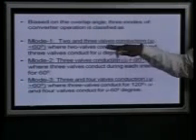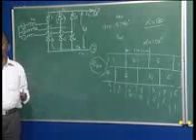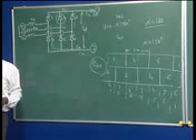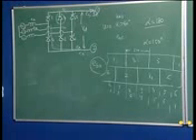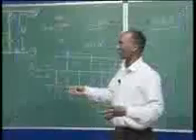No doubt this is very common, because the overlap angle u is not 0. It will always take time, because the current from one valve to another will take some time; it is not instantaneous. So this mode 1 is very common, but mode 2 and mode 3 are not so common. They may happen when there is some fault or problem in the AC system, and we can land up in the condition where 2 or 3 valves are conducting.